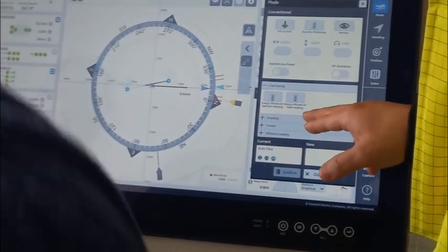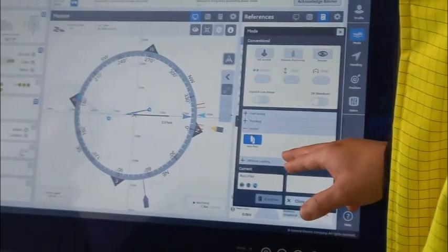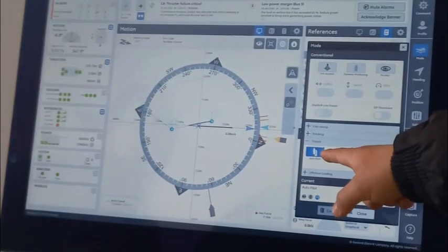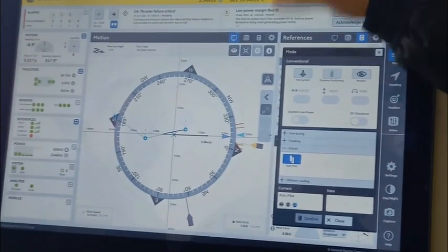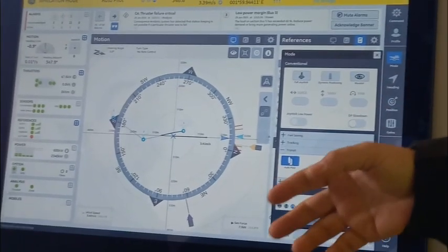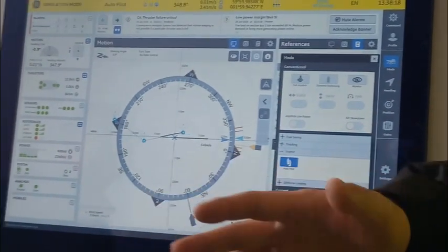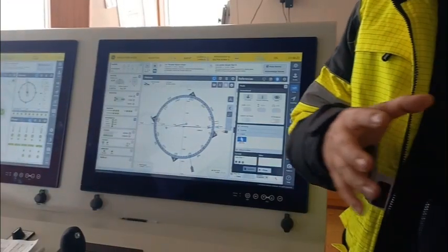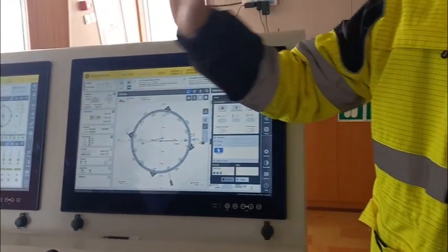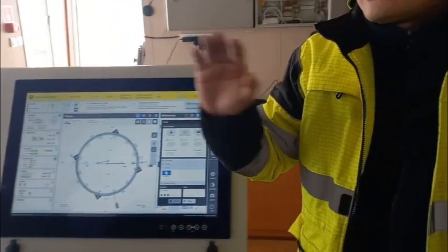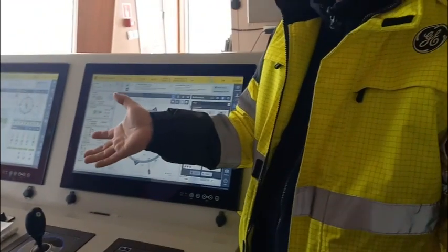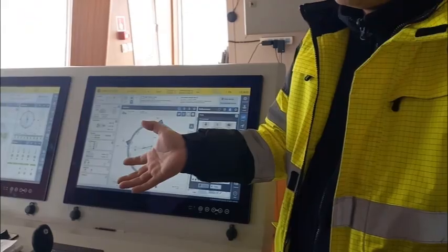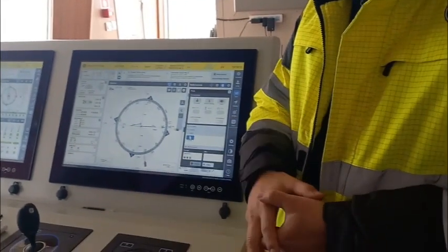That's all the modes we have. All right. So during sea trial, I will tune the autopilot, DP, and auto sail. All this will be demonstrated. Apart from the ship follow, the ship follow will require a vessel in front, and then we follow them with the fan beam. Then we don't have the remote target vessel available, so this one will not be available.